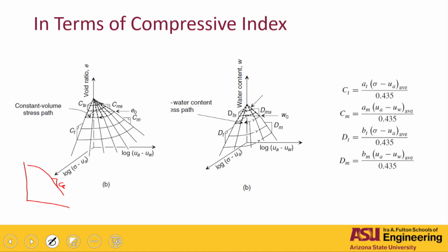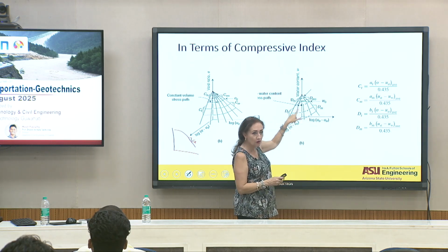Now, if you get into the water contents, this is the water content change with respect to suction. And you've got this slope in here, and this is the water content change with respect to net normal stress, all right? The surfaces don't go parallel to each other, this one might be much lower than the other one. But do you recognize this relationship? What is this relationship? The change in suction with respect to water content.